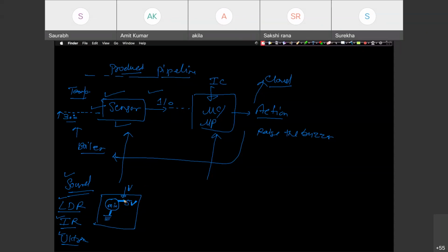What I did is connect a resistor here, which could be called a pull up or pull down resistor. If I connect my resistor here on the ground side, it will be called pull down. And if I connect this resistor on the 5 volt side, it will be called a pull up resistor. So RP, right? I have a resistor here, and this is my terminal. Suppose I'm talking about the data terminal. This is the data terminal.